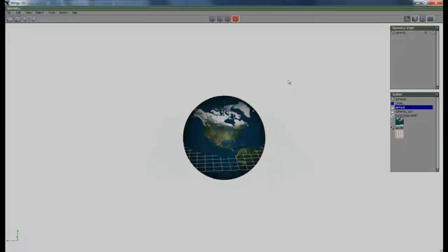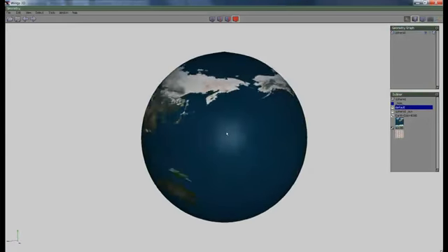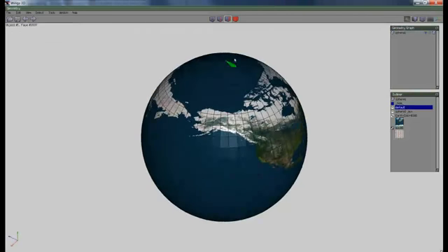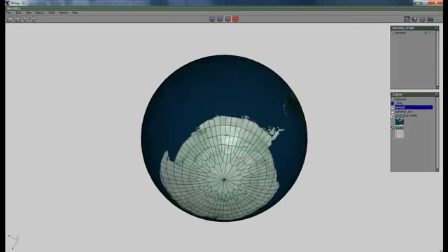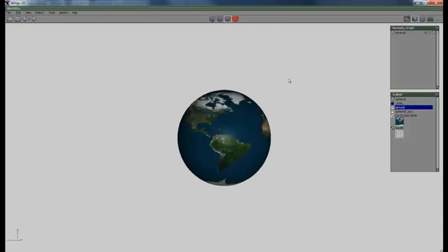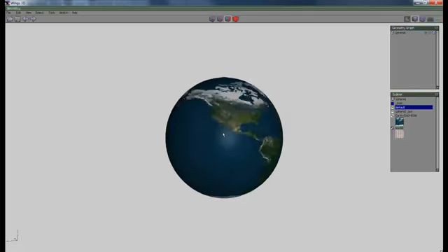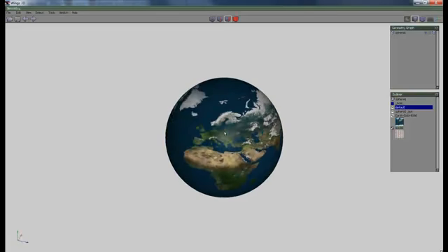I can just select this and smooth it a couple times using the S keyboard shortcut, and there we go. We have an unwrapped sphere with a little bit of pinching at the top because there were triangles and stuff. But I'm not really too worried about that right now. There we go. That's a sphere unwrapped, just as easy as all the rest.